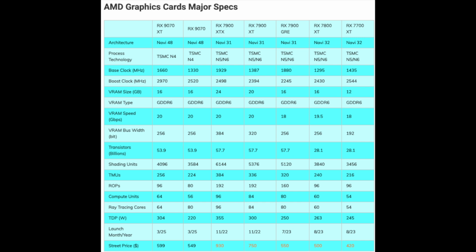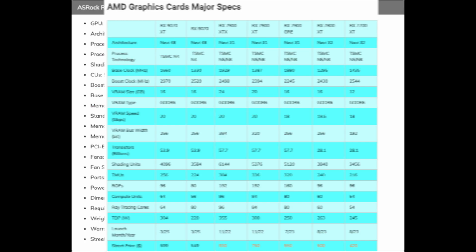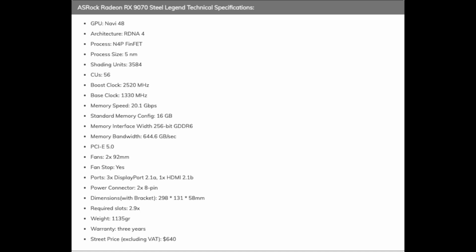Lastly, to improve ray tracing performance, AMD introduced oriented bounding boxes to reduce or eliminate false positives in ray triangle and ray box intersections, and a dedicated ray transform block to help with transformation. A dedicated ray transform block is specialized hardware in GPUs designed to accelerate the transformation and manipulation of rays during ray tracing. It handles tasks like ray object intersection calculations more efficiently, improving overall ray tracing performance.